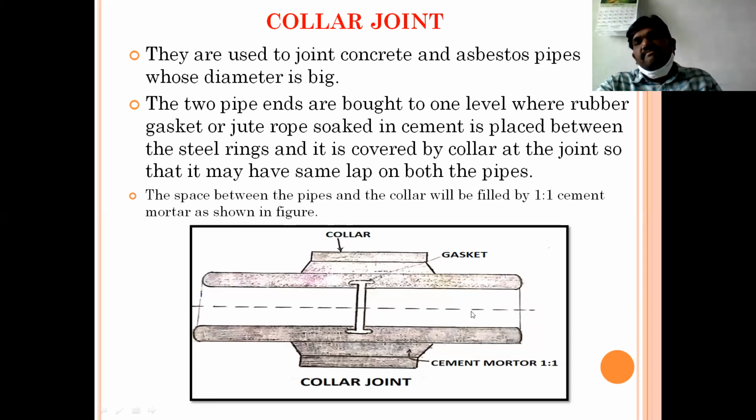Understand? See, the two ends are kept close tightly to each other. One rubber gasket will be there. Above that, 1:1 mortar will be placed. The collar will be fixed.